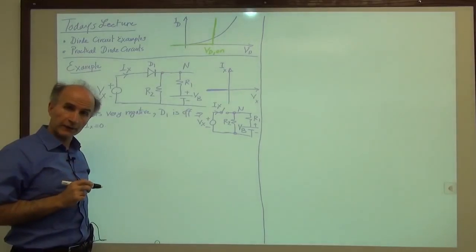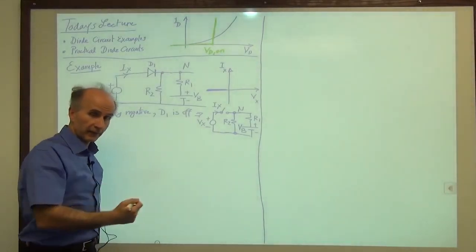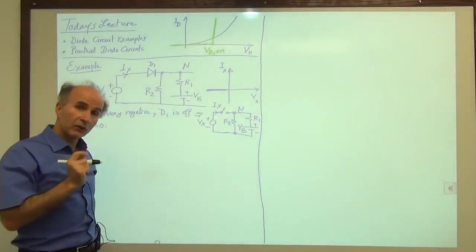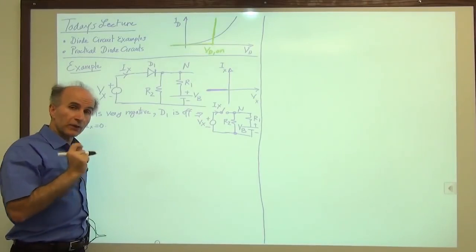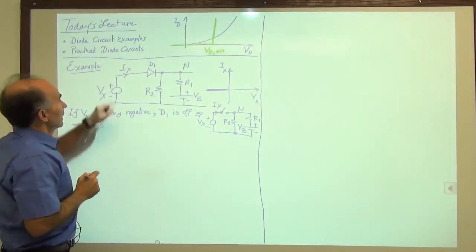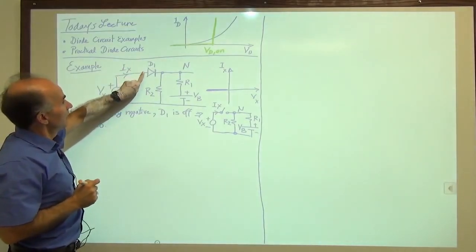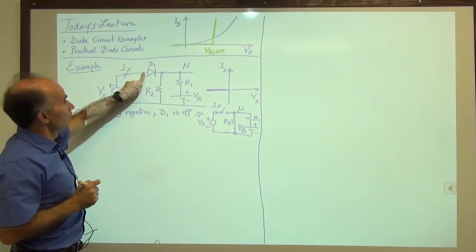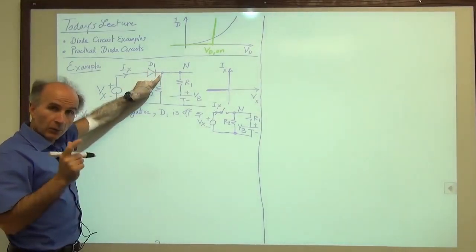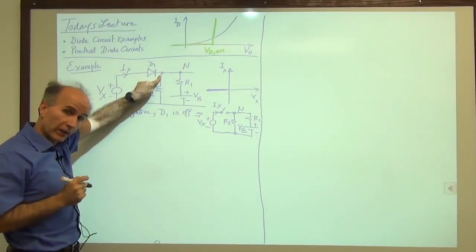Okay, so far so good. Now let's go ahead and increase Vx towards positive values and ask at what point, for what value of Vx, the diode turns on. Well, this voltage has to go up and up and up until this voltage is more positive than this voltage by 0.7, 0.8 volts, by VD on.